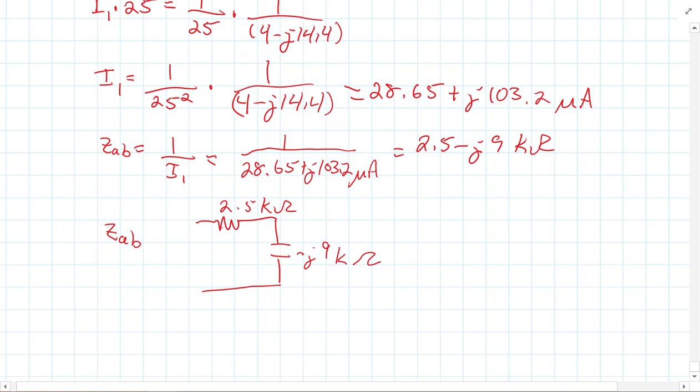If you want maximum power transfer, you're going to need to cancel out this capacitive load effect, and you do that by putting an inductor in series of the same value. We'll cover that in more detail, but there is a reason for wanting this as opposed to just, hey, here's a problem to do. Alright,